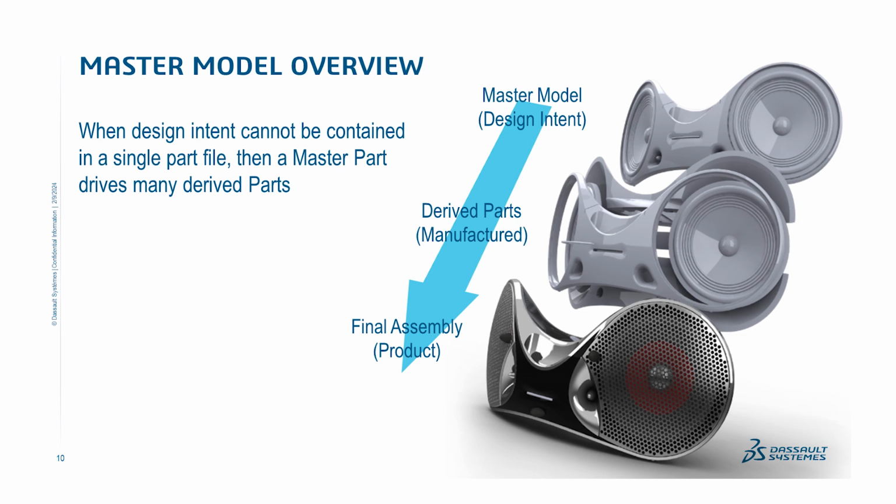So the beauty of that is, especially with consumer products, a lot of the part lines are not linear or not simple, and to try to create each of those parts independently from each other would be very, very difficult. So for consumer products, the master model technique is a must and has been greatly adopted for consumer products.